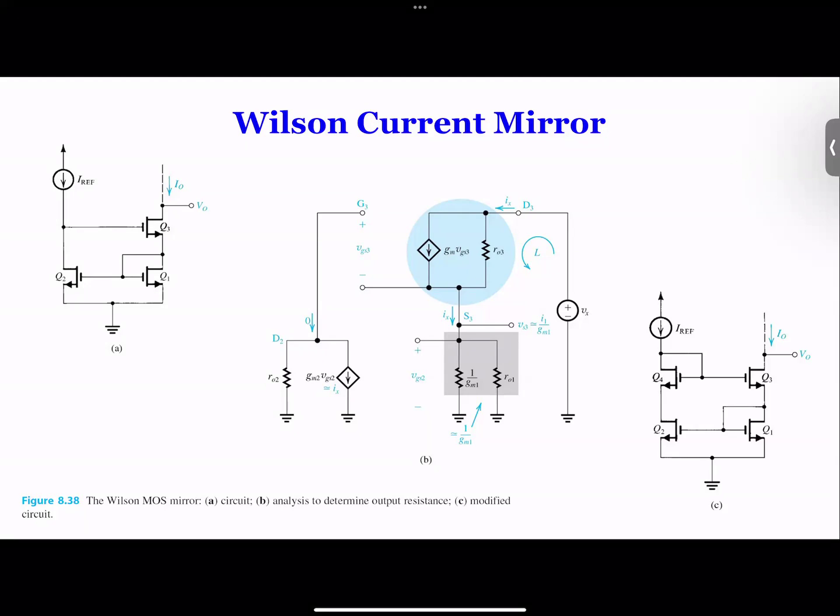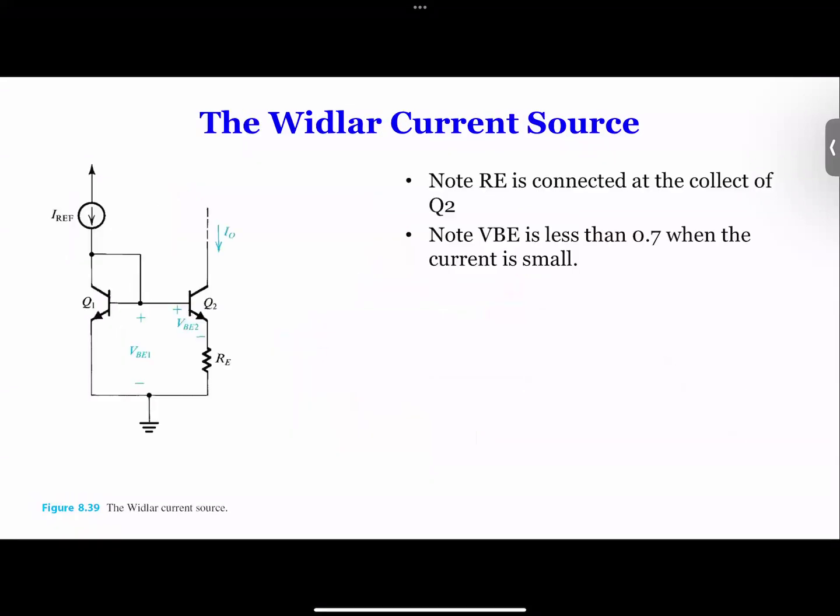When we get to really high-speed computing, with millions of transistors on a single 1-inch wafer, you will say, oh no, that's not true. So that's why they try to do this, to do the balance. You can do the analysis on this one as well. If you do the small signal equivalent circuit, you find that there's another one here. So there's another circuit up to this point, but you can still do it. So that's a Wilson current mirror.